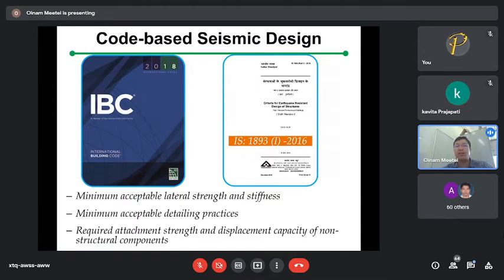If you open any of these design codes, you can find the yield force and the base shear force, everything in terms of newton, kilonewton, kips. But when it talks about the performance point, it is expressed in terms of drift: 2%, 1%, 1.5% drift. That level only people will talk about. The same thing happens in your limit state design.